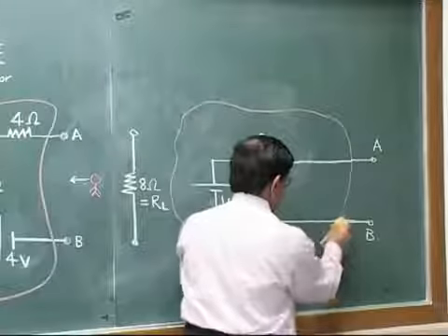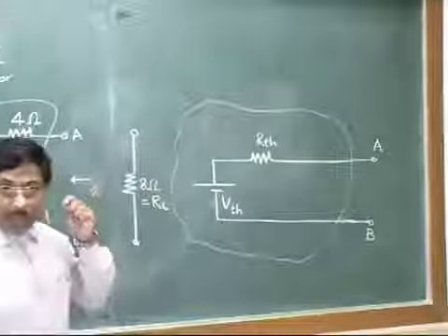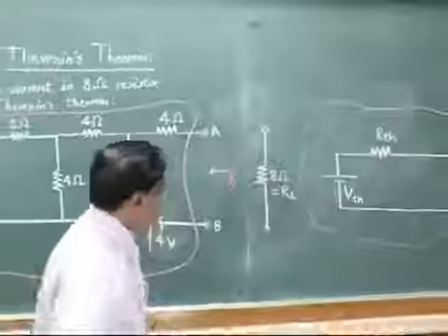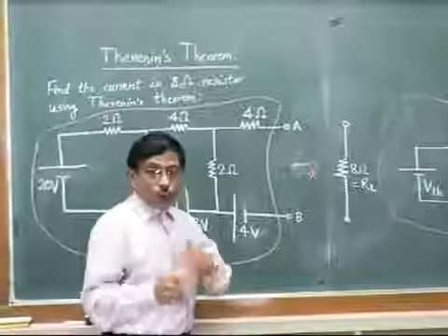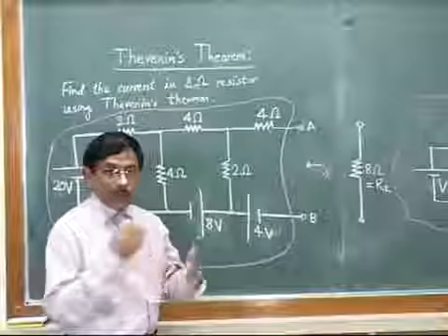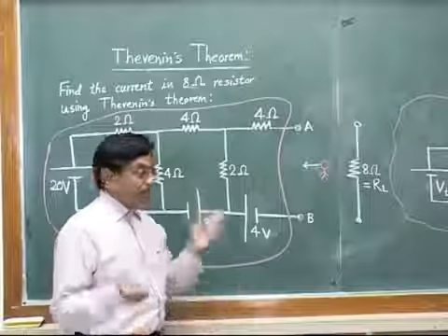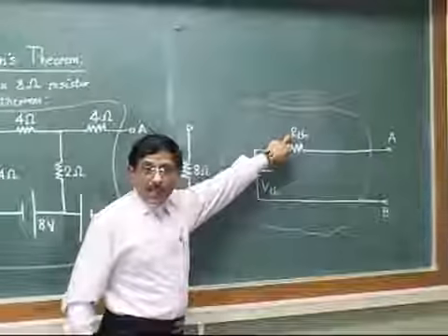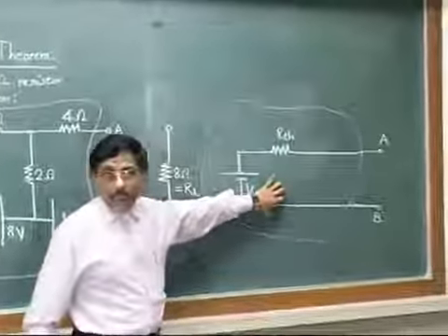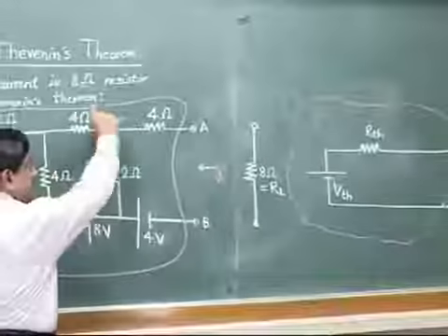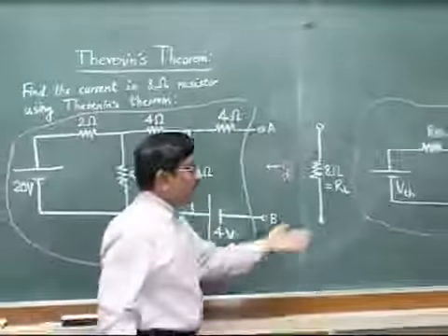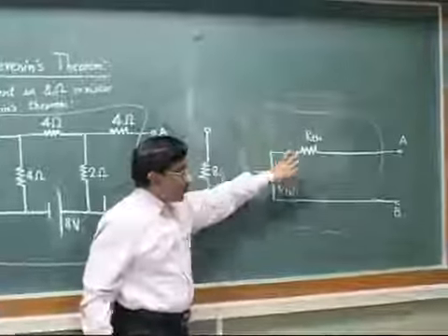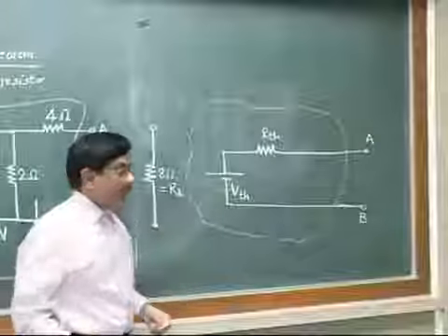Like this. Okay, so the fundamental or the central idea of Thevenin's theorem is that you should treat or operate on this circuit in such a manner that you finally decide what is VTH, single value, and what is RTH. And once we do that, we can replace this entire circuit in the box with the equivalent values. And once we do this, the next step is very simple.